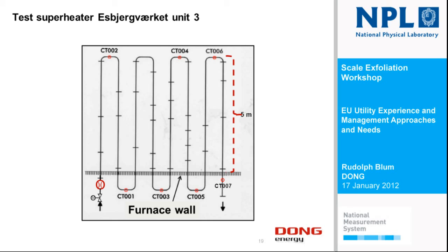So we can measure exactly the steam running through this installation, meaning that we can measure the heat flux and heat pickup by every coil, because we have external measurement of steam and metal temperature here. So we know exactly the condition of this test rig, which you normally don't have in most experiments shown in literature from service-exposed material in boilers. You know nothing about the real test condition. This led to very precise results.